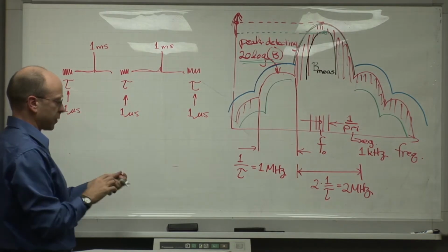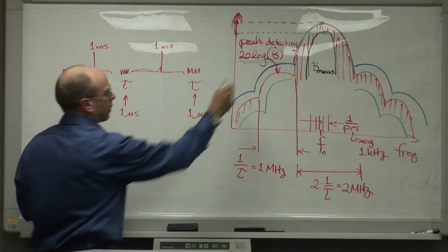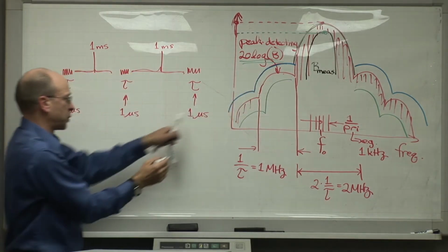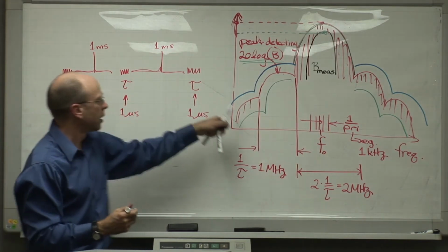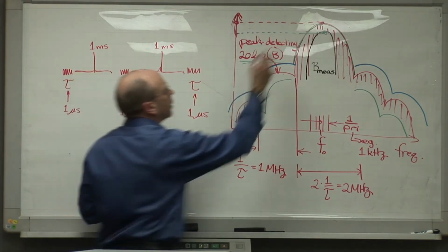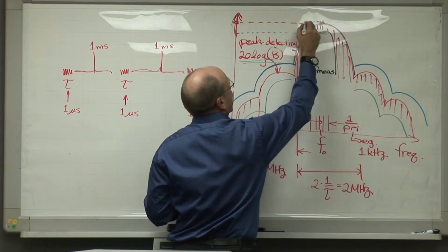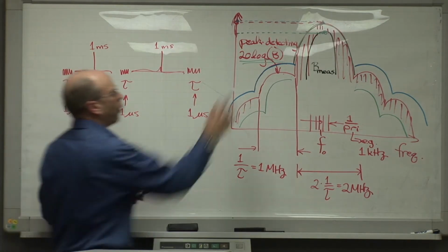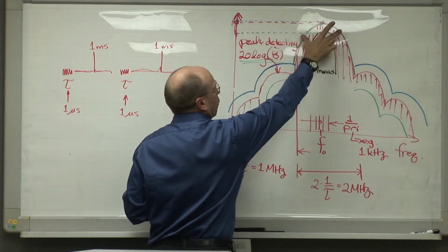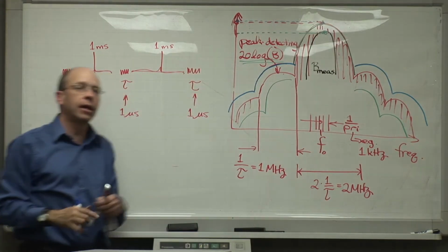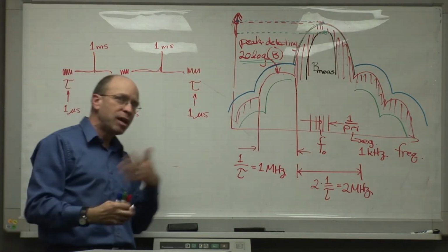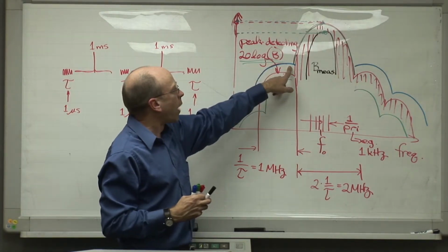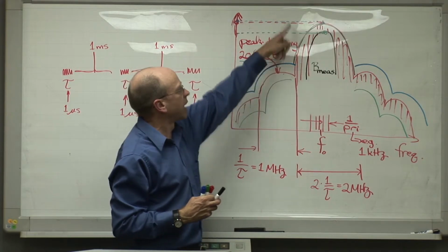And then, here comes the tricky part, when we go to the third bandwidth, this wider bandwidth, where the power out here in the out-of-band part of the spectrum, and for that matter, out in the spurious part of the spectrum, so through all the unwanted emissions, is going up at 20 log of the bandwidth, what do we measure? The same value. The power stops going up at the fundamental when our measurement bandwidth equals or exceeds the width of that central lobe. Now, admittedly, there is a fraction of a dB more power, maybe a dB more power, that we get as we widen ourselves out to this wider bandwidth that I've drawn in blue here, but not by much.